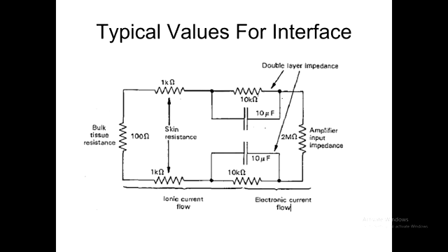Are we trying to find the equivalent resistance from one end to the other? The name of the game is to try and find a time constant that typifies this circuit, right? And with that, a capacitance will experience an equivalent resistance. And we know that this capacitor, for example, is going to experience something less than 10 k ohms, because it's already got 10 k ohms in parallel with it.